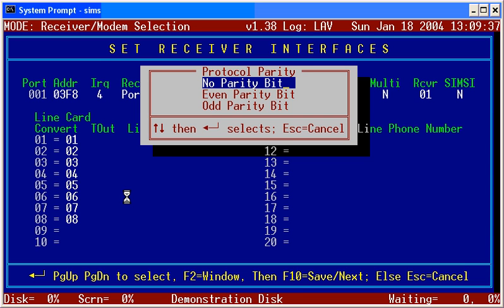If you see garbage coming in, then you should know the baud rate is wrong. Now, know that if you're dealing with a PCI card, the divisor for those baud rates is different than an ISA card. So we recommend that if you use a PCI card, and if you've had the selection turned on from SIMS personnel, and by the way, it's turned on in the demo, so you can always try the demo, you must use an address above 1000. If you use an address above 1000, then the SIMS program will know that it's a PCI card. We're talking about the address or port address. It will make the necessary adjustments in the divisor.